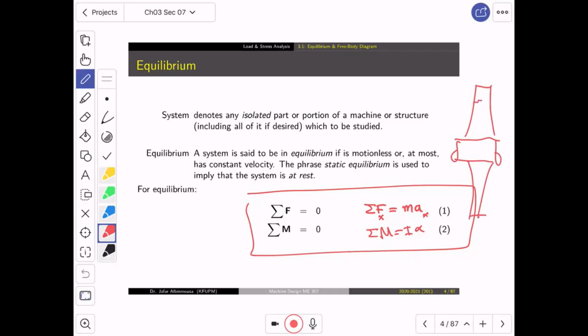If there is a crack over here, and this turbine is rotating, which we all know from industry, at nearly 30,000 RPM, 30,000 revolutions per minute, that's a huge rotational speed. If you convert it into centrifugal forces, it's not little. That force generated by the centrifugal acceleration might propagate the crack until you have the whole thing broken. In that case, you have no choice except taking the inertial effect into the picture.